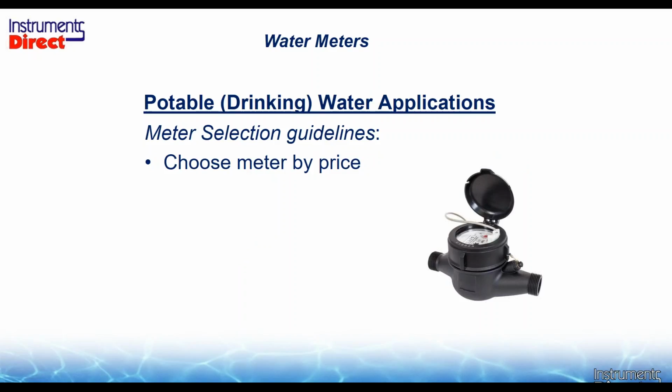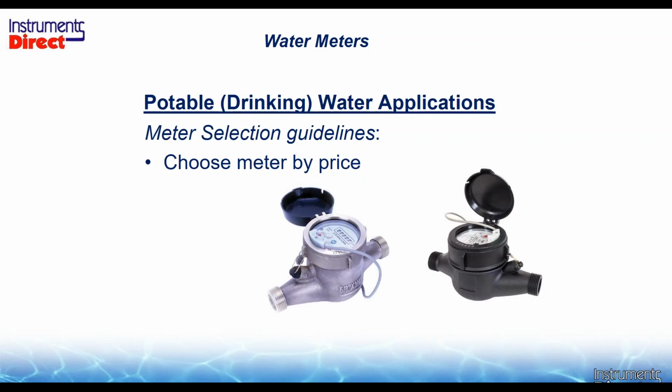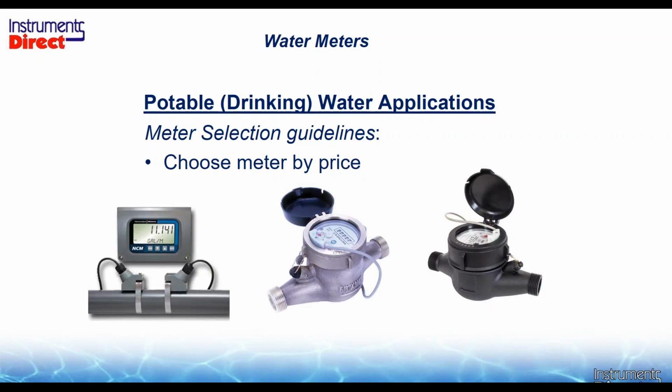Choose your flow meters by price. So if you're going to select it by price, we just said the plastic meter is one of the least expensive meters that you might have. And it costs a little more to get the same thing made out of bronze, but it's much more durable, so there's a trade-off there. Or I don't even want to put a hole in the pipe. Now I just want to clamp on an ultrasonic flow meter.